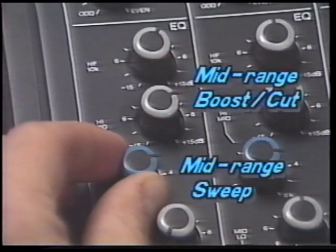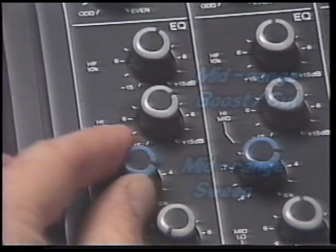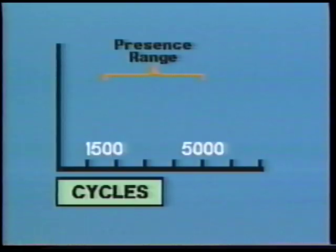So what I often do is find the fundamental tone that I prefer, then move the frequency of the equalizer up slightly. This brings out the basic tone, as well as the upper harmonics and overtone colors of the sound. For example, if the frequency I like best is around 4,000 cycles, I'll bring the frequency setting of the equalizer up to 5,000 or 5,500 cycles. The result will be a fuller texture with more clarity. It'll also make the sound seem to be less electronic.